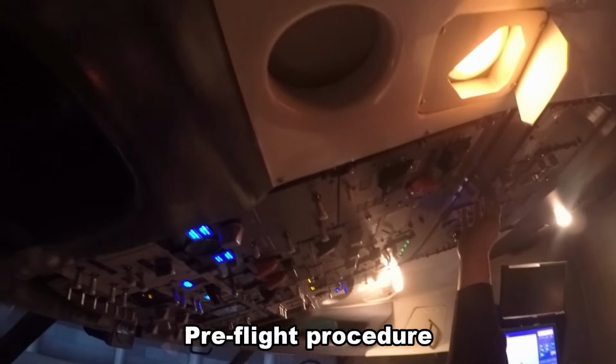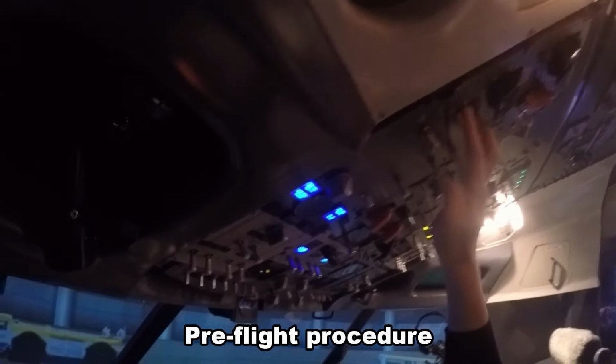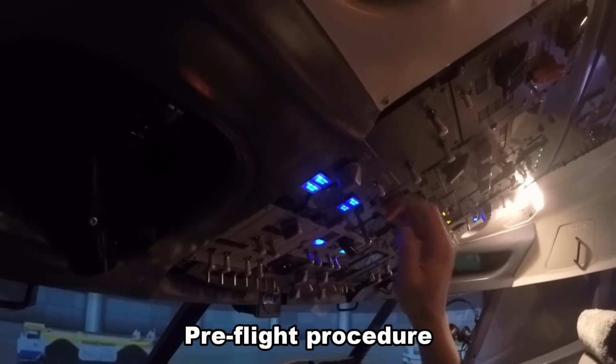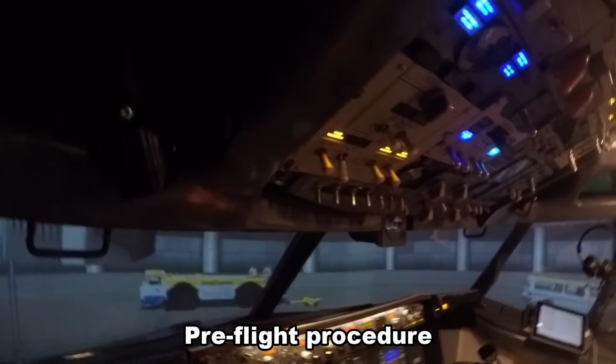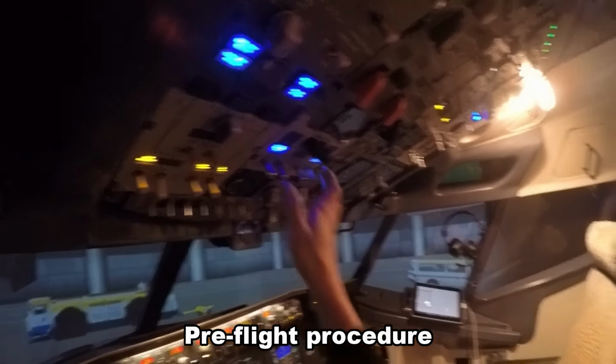Make sure that our IRS is set to nav, the yaw dampeners are on, navigation, transfer and display switches are both normal, and auto. Crossfeed is off. Fuel pumps, we'll just have the forward left one on. The APU is already running.